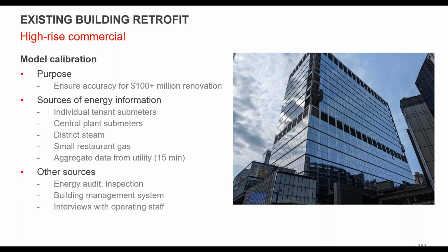Like 0 on minimums, 0 ventilation, reheats disabled. I think there's a lot. I mean, it depends, Sean, on what the intent is for what you're trying to show. Those boxes were not going, the ventilation was not going to 0 at night. It was still whatever the background minimum flow vent would be required. But I think it just depends on the client, what you're trying to achieve. Like, again, it's apples to apples comparison of system to system. So in that case, it's not like a full compliance model where you would have to be showing the ventilation at night. It's more to show the changes made to two similar models that have 2 different chillers in them.